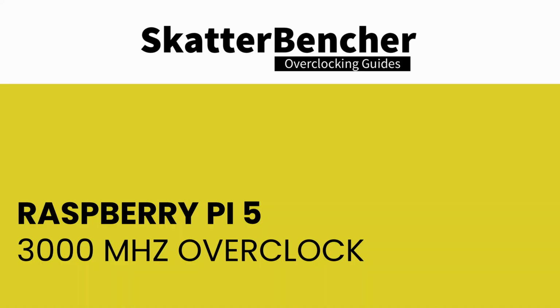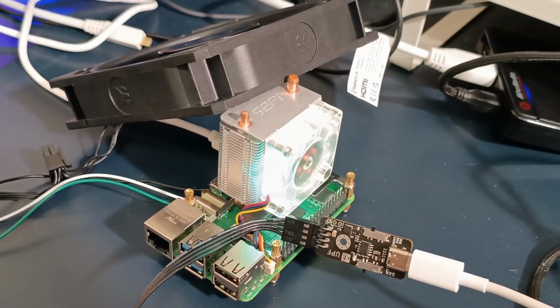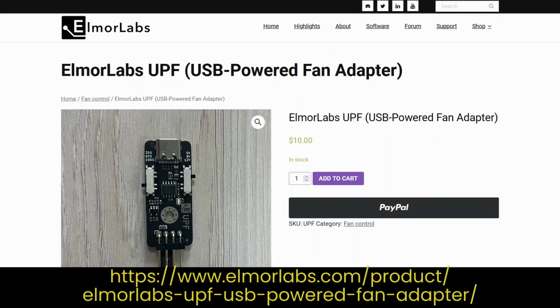The final piece of the puzzle is to increase our clock frequencies. I further increased the ARM cores to 3 GHz, and I also overclocked the V3D engine to 1.2 GHz. The additional voltage was too much for my small tower heatsink, so I added an additional fan to cool the heatsink. A quick shout out to Elmo Labs for providing the UPF and making it easy to use a standard